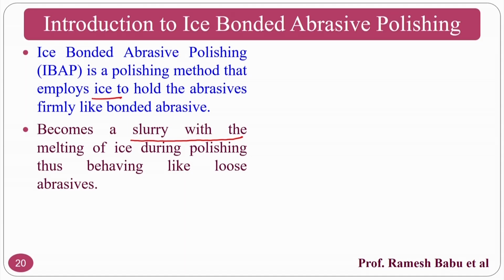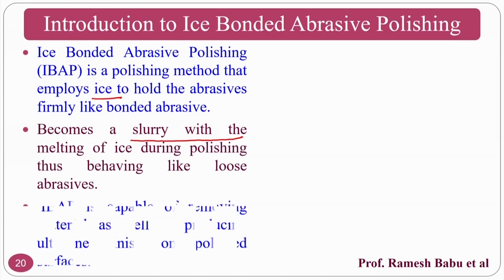Whenever it becomes a soft bonding, the debonding of abrasive particles will take place and new cutting edges will come. So, dressing is not required. Okay. Maybe truing may be required if you make a wheel type of tool, but if you see the polishing pad or something in the upcoming slides, you may not require that also.